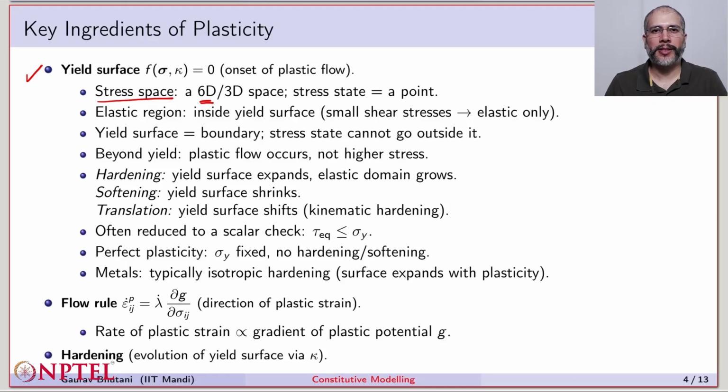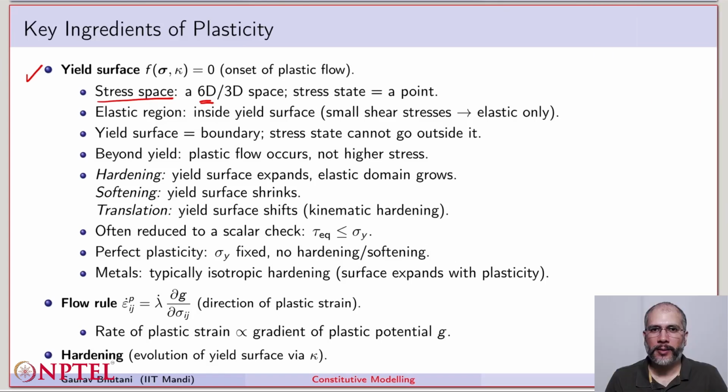If the state of stress changes, that basically means that you move to a different point or a different position in this 6-dimensional stress space. By the way, don't confuse this with the stress plane that we talked about earlier, where we had drawn the Mohr circles.